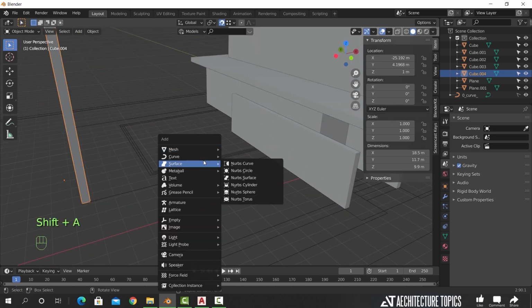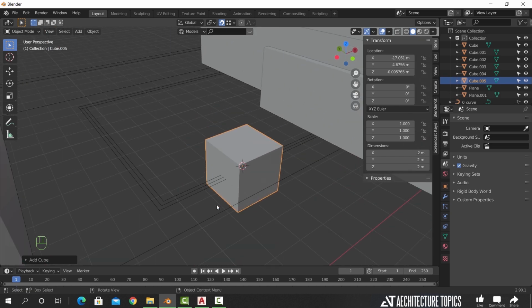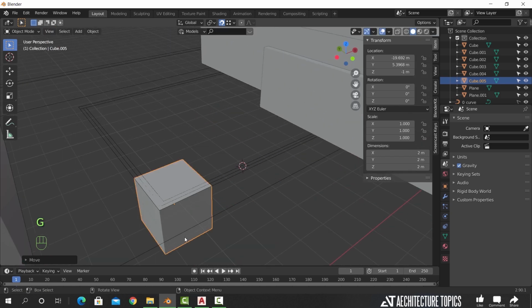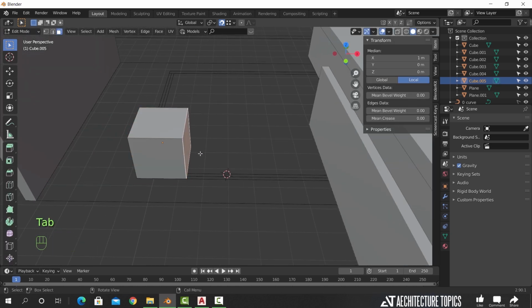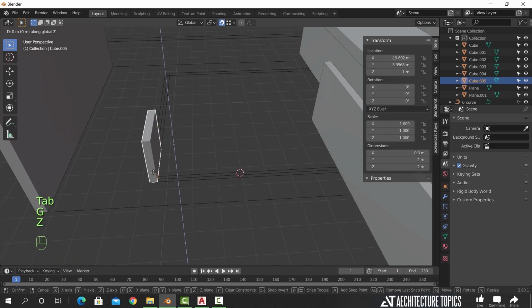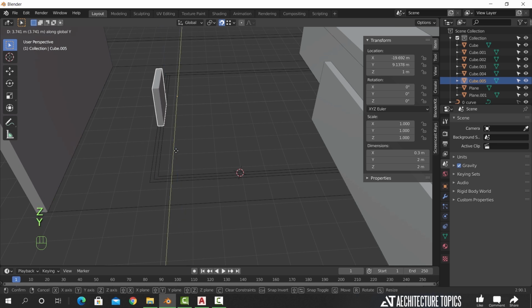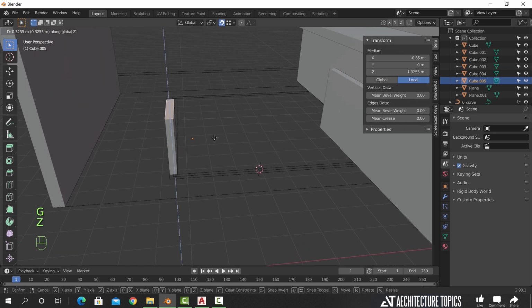In those interior walls, I will add a cube and just cover this area. It won't show up that much in the render, so make it as you see fit. I think a garage would be nice here. So as before, snap the cube to this corner, fix the height to match the main mesh level, and inside edit mode, switch to face selection and use the extrude command to finish the walls.